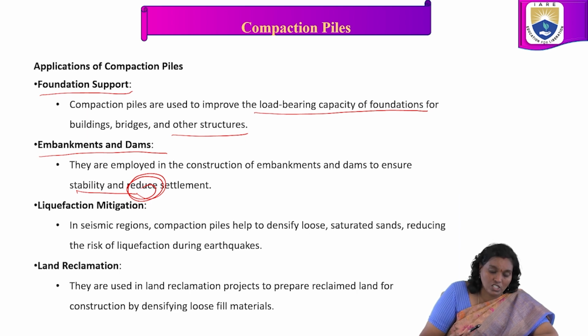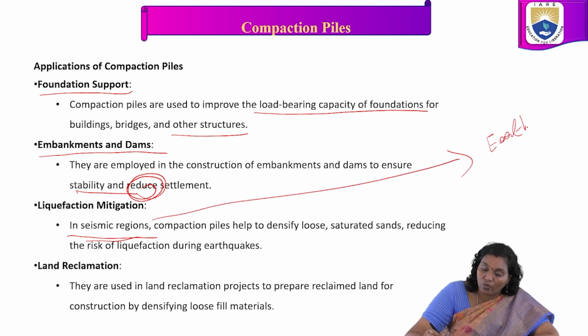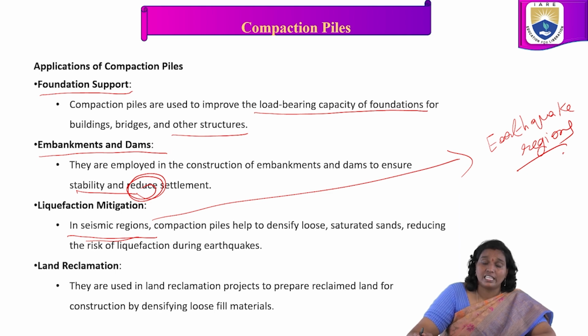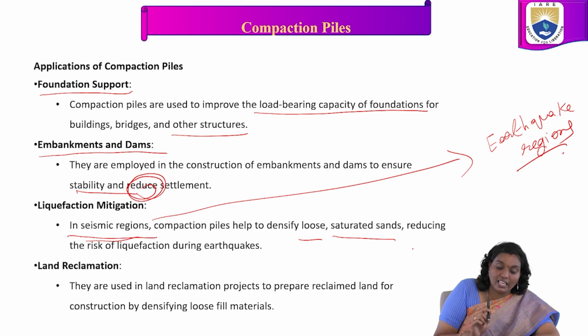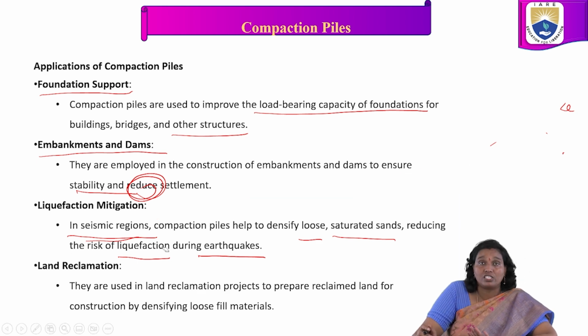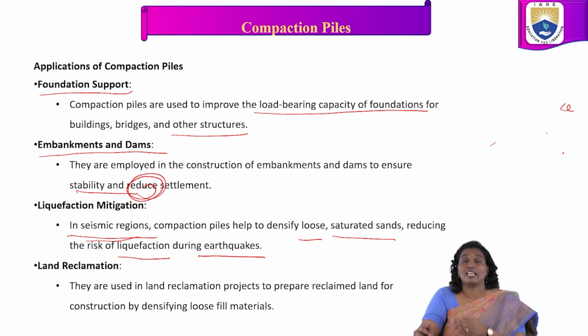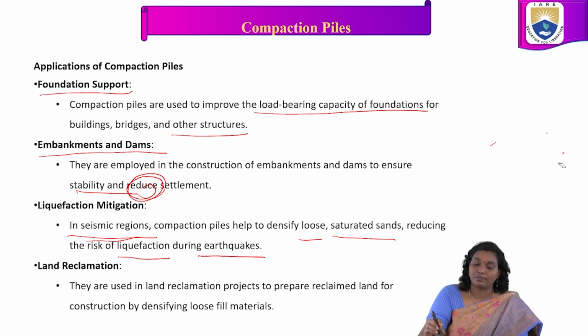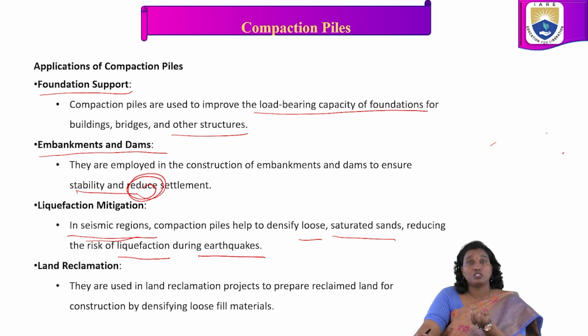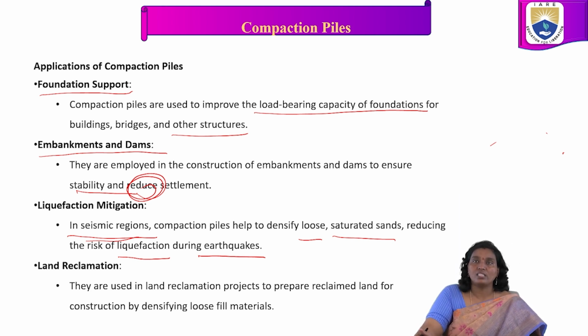The next one is liquefaction mitigation in seismic regions. Whenever it is a seismic region, we already know the effect of earthquakes. This is also one of the important considerations, based on which type of construction, where the site location is and which type of zone it is as per the seismic region. We have to understand the compaction piles, and this solution also reduces the risk of liquefaction during earthquakes. Compaction piles help to densify loose, saturated sands, reducing the risk of liquefaction during the earthquakes.